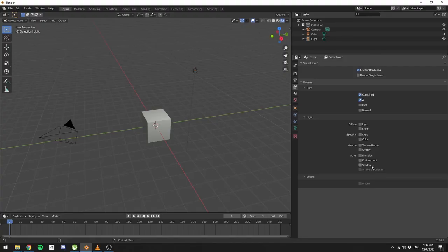You have shadows, and how Blender works is it renders each of these things on a separate channel, and you can export those separate channels. For example, if you're making a movie, you can import each of the render passes in Nuke, which is a program for composing. And in this program, you can change each of the passes. For example, you can saturate the colors, you can boost up a little bit the lighting, you can change the shadows. So from here, you can work with the rendering passes.